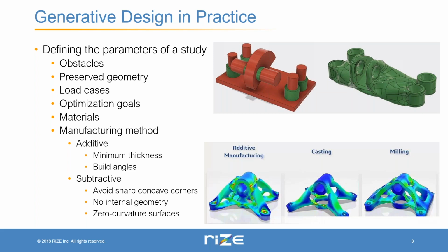So because generative design automates so much of the process of making decisions about where to place material and where to make things stronger and which places can be weaker, you don't need that level of mechanical design expertise. However, you will still need to have some knowledge of the program that you're using, because what generative design allows you to do is set up the boundary conditions, or the basic constraints of your system, and then it will create a design around that.